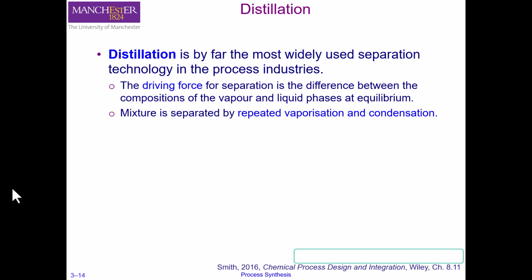As we discussed in part one, in distillation, separation is achieved by exploiting the difference in volatility of the components being separated. Also, in distillation we take advantage of very large density differences between the liquid and the vapor phase, which are separated by using the gravity effect.